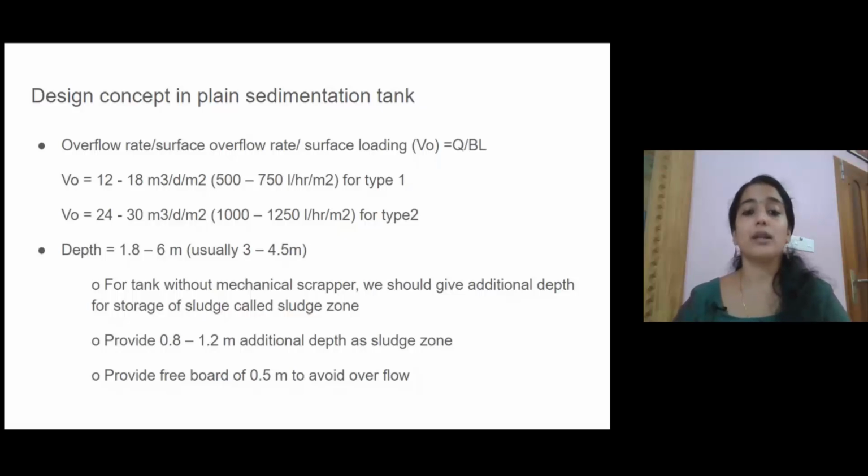The second one is the depth of the tank. Basically it is between 1.8 to 6 meter. Usually we consider it between 3 to 4.5 meter because it is apt for a medium-sized population water treatment system.